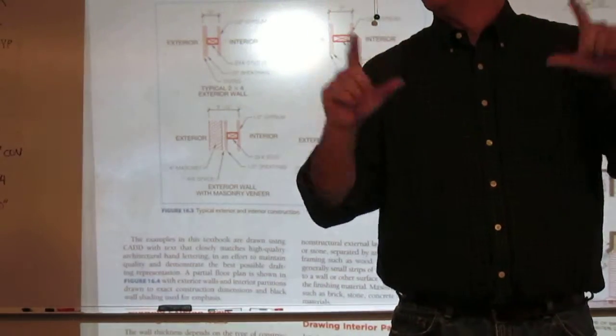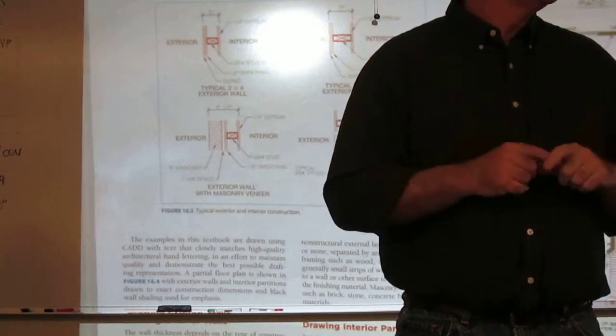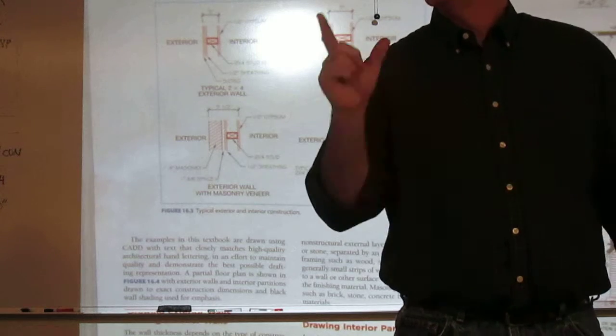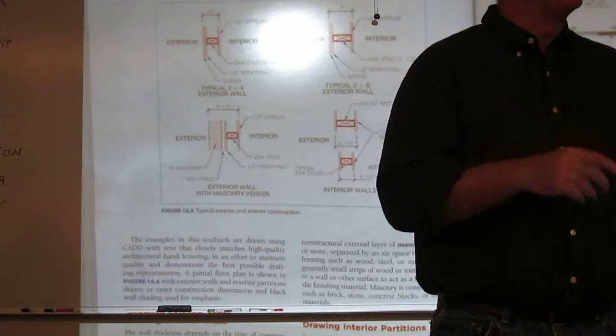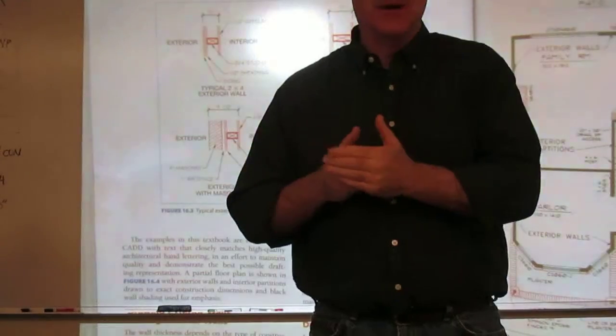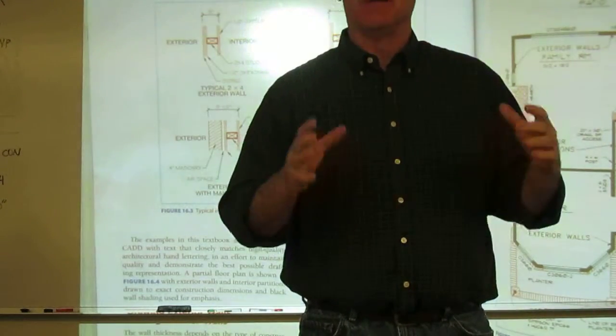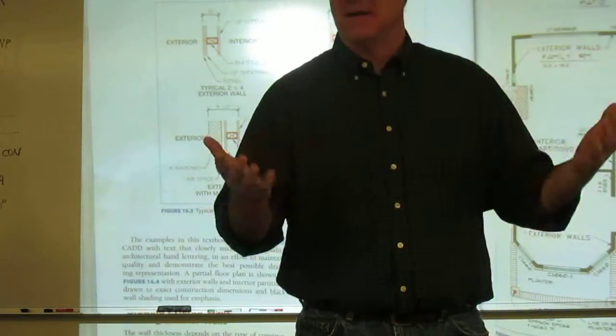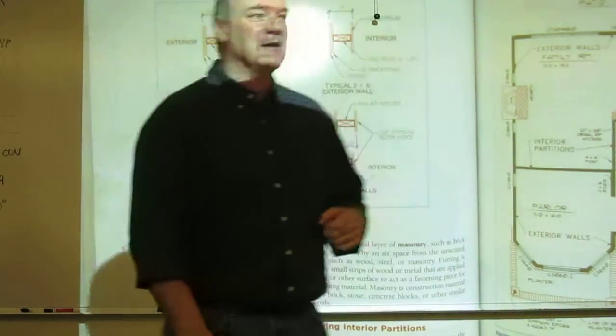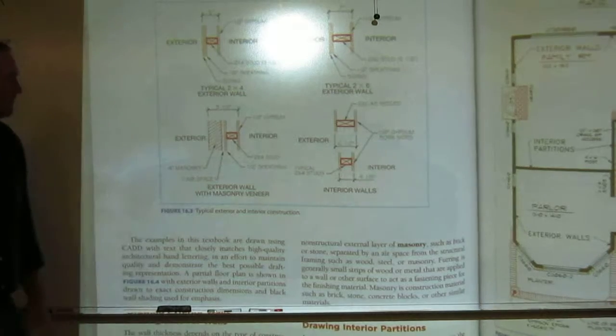Just a little caveat, and I'll say this later, if you're going to hatch your walls, I don't have a problem with that, but don't do it now. You're in the process of developing where these walls go, and if you're going to be moving them and stuff, you got hatching in there now, you're going to make everything more complicated, right? Because now you got to move hatches with it and everything else. So leave that off for now.